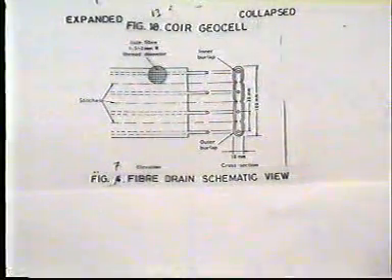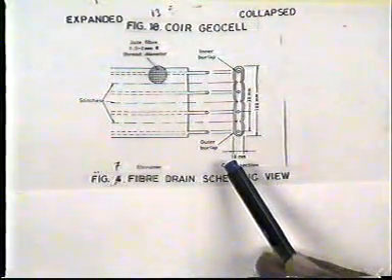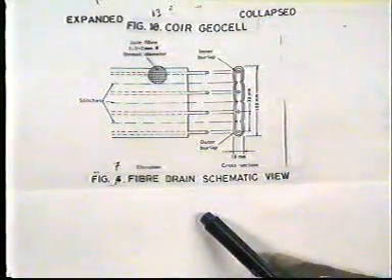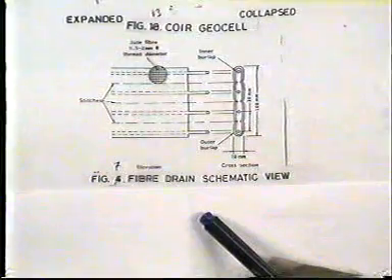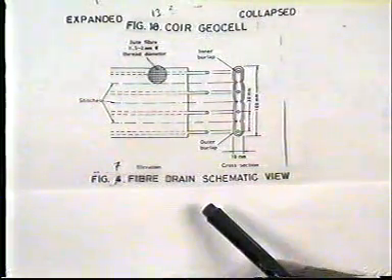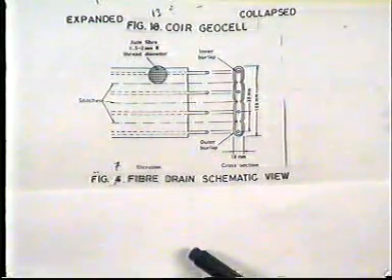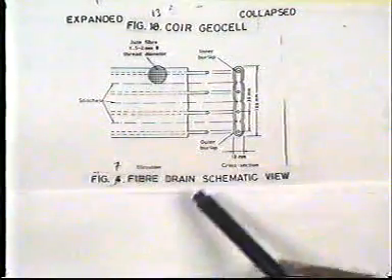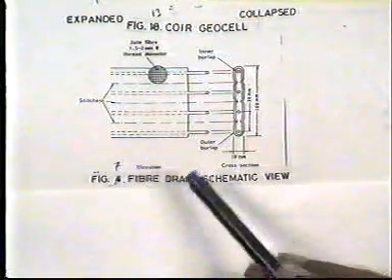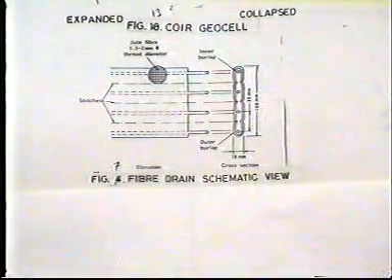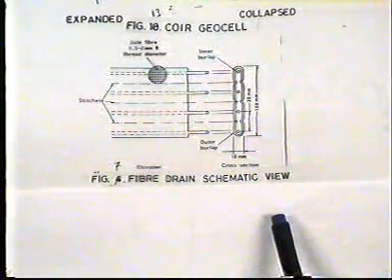The construction of buildings on soft clay soil leads to the long-term settlement problem, which is best dealt with by pre-consolidating the clay soil until the anticipated settlement under the design load is enforced completely or partially prior to construction.